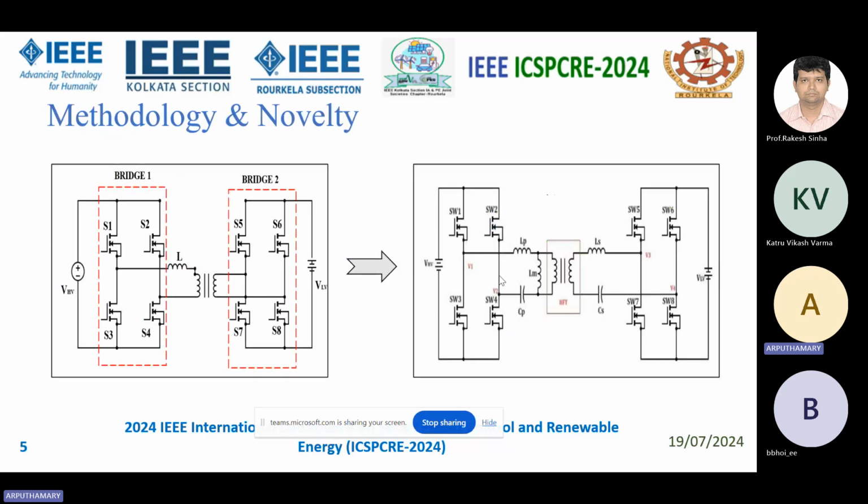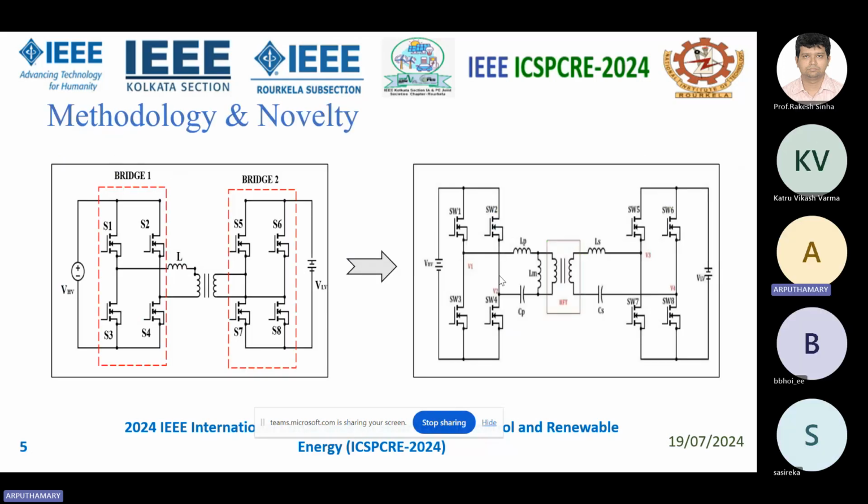So the first box is about the conventional one, the dual active bridge. In the dual active bridge, only the leakage reactance L will be present. So the soft switching mainly occurs by means of the current passing through the leakage inductance. Here the zero voltage switching range is very small compared to the proposed one. The rightmost part is my proposed one. Here I have made some analysis and found the resonant tank, which will give a higher ZVS range when compared to the conventional dual active bridge.